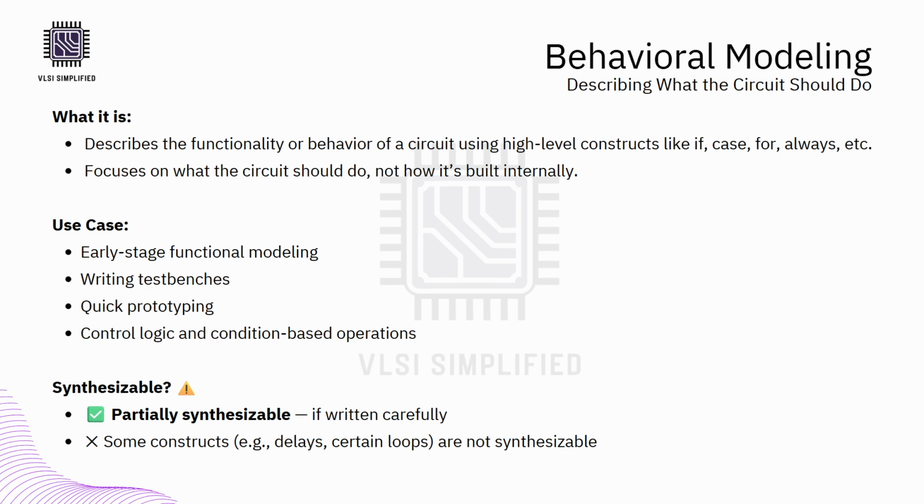Verilog gives us a rich set of high-level constructs like if, case, for, and while, along with blocks like always and initial. Using these, you can quickly describe complex decision making, control flows, or functional logic. This level is widely used in simulation and test benches because it's easy to model and test behavior without worrying about synthesizability all the time.